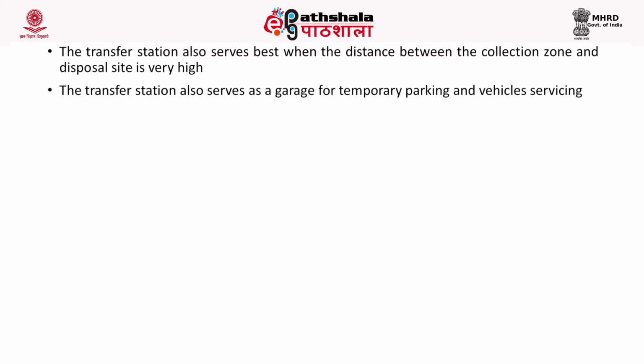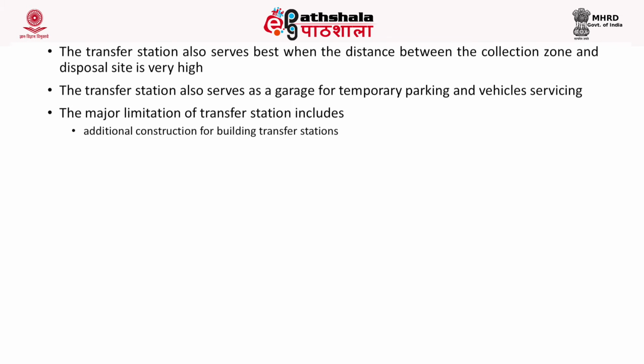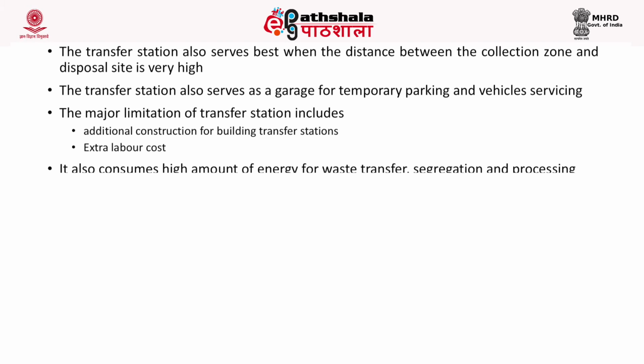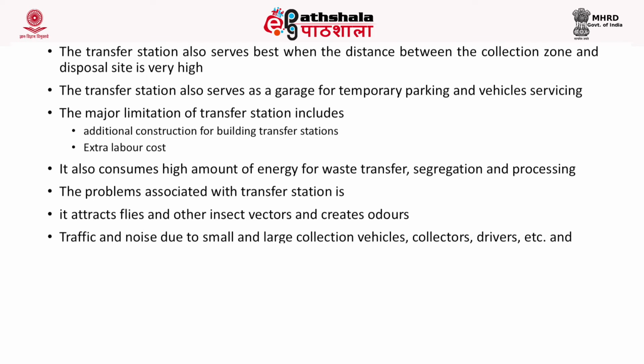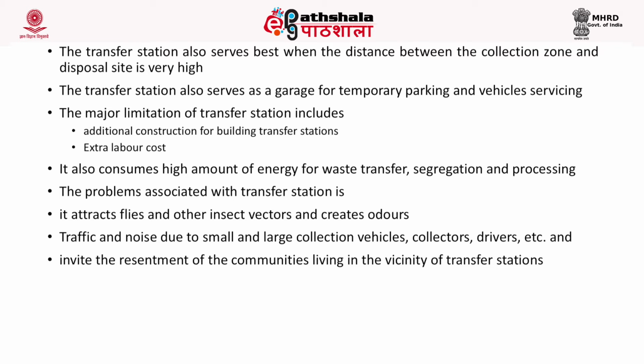The transfer station also serves best when the distance between the collection area and the disposal site is very high. They can act as a garage for temporary parking and vehicle servicing, I mean the collection vehicle parking and vehicle servicing. Now, you have two main limitations for this transfer station: it involves extra labor and additional construction cost for building the transfer station. It also consumes a high amount of energy for waste transfer, segregation and processing.